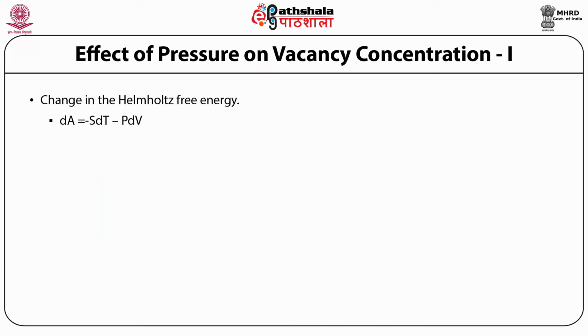Now first we are discussing the effect of pressure on driving force and vacancy gradients. We have already discussed in the previous modules the driving force for sintering, and we have seen that it varies with 2 gamma by r. But on the physical level, an additional vacancy gradient is set up due to the applied pressure between the grain boundary and the neck.